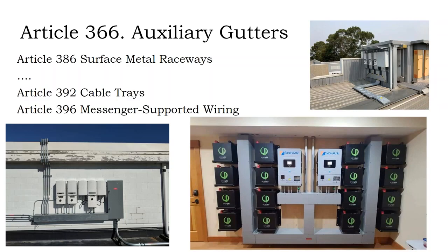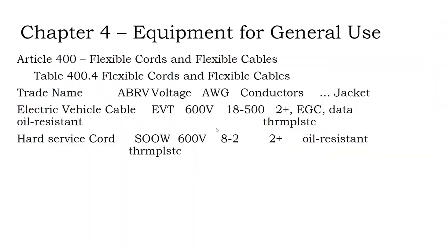If you're using a wet rated conductor like THWN2 that's not rated to go outside a conduit, you would still need to respect the environmental ratings of the conduit. Just because you're using rain tight fittings on EMT conduit doesn't mean the inside of that conduit is in a dry environment.